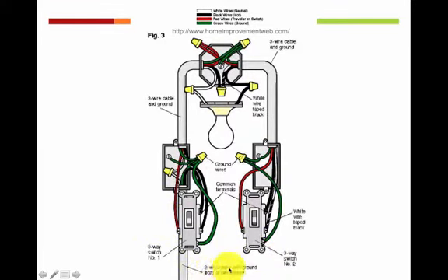Here we have a wire. It is your typical probably 12-2 wire. What would be typical, actually, is that lighting uses 14 gauge wire, which is a little bit of a smaller wire, because lighting circuits are usually only 14 amp or 15 amp circuits. If you go downstairs into your breaker box, or upstairs, depending on where your breaker box is, and you look in there and there's a 15 amp breaker, or a 15 amp fuse if you have an older home that has a fuse box instead of a breaker box, 15 amps is your typical home lighting circuit.